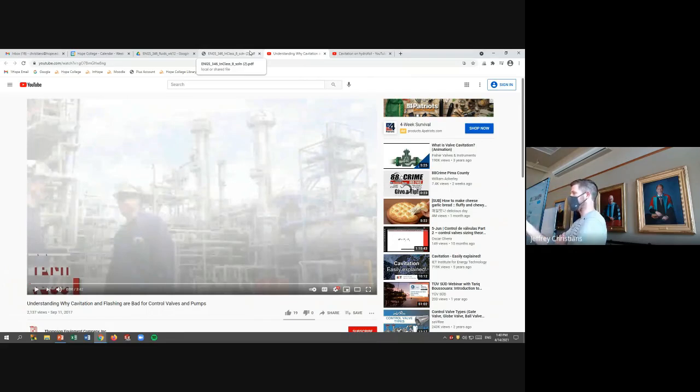What does that mean about kinetic energy? Where did that kinetic energy come from? If pressure goes up and kinetic energy goes up, we just violate conservation of energy. So if kinetic energy goes up, pressure has to go down. As you go underneath that valve, I'm assuming most of you drew pressure going up. And all of you are wrong, because it can't go up, because the energy for kinetic energy has to come from somewhere.